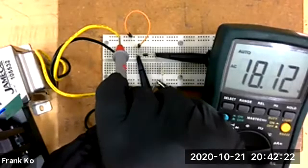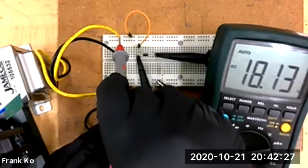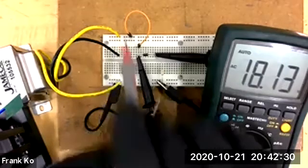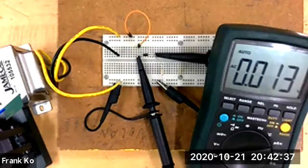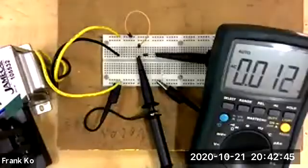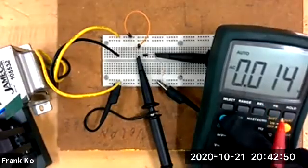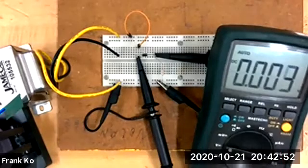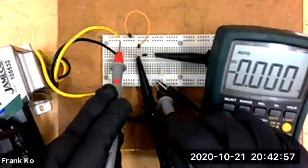Okay, my input voltage in RMS on my transformer, 18.13 VRMS. So AC voltage measured on my digital multimeter, 18.13 VRMS. And is there any DC voltage measured on the multimeter? So select this to go to DC. Oh, sorry, DC. And I go to measure the DC voltage from here to here.